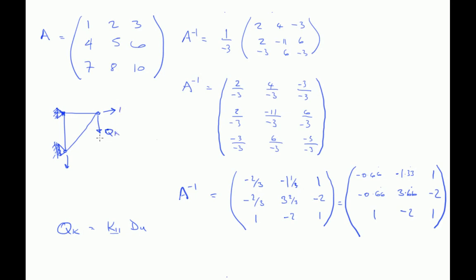Let's say that's on degree of freedom 1, 2, and 3. So there's no load on that degree of freedom, no load in that degree of freedom, and a load of, say, 2 in that degree of freedom. So we have a system of known loads, the stiffnesses, and then these unknown deflections in 1, 2, 3 degrees of freedom. And then for completeness, we'd also have these fixed nodes, fixed degrees of freedom, I should say.